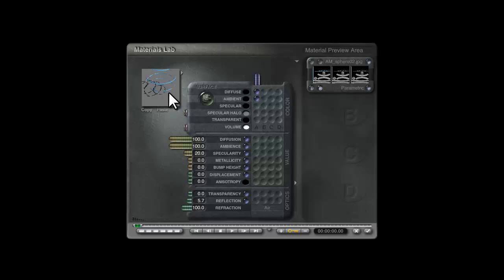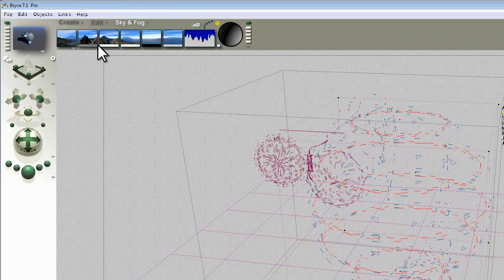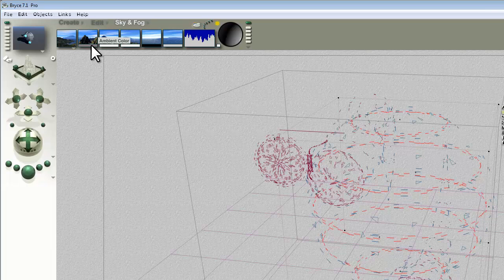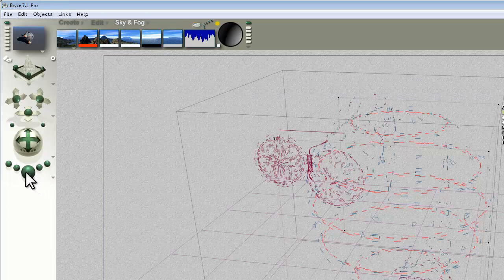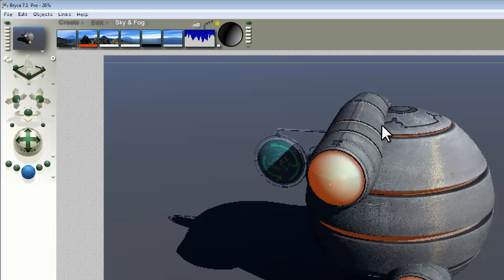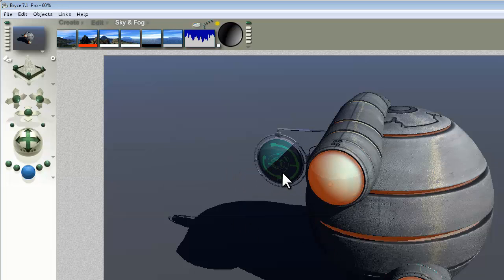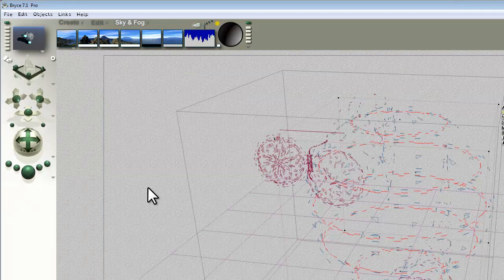Right. If it's just a light, then we can just use the ambient channel to create that glow. In fact, before I modify that, I'll show you. Right, the ambient channel is provided its power output from the global ambient colour. So if I give this a quick render now, and then we can see that metal's been updated, and then change the global ambient colour to something dramatic, and then look at what changes, you can see what's deriving its output from that channel. So this little display there, these lights here, these lights in the bands. So okay, and then if I want maximum output from that channel, I just set it to fully white.